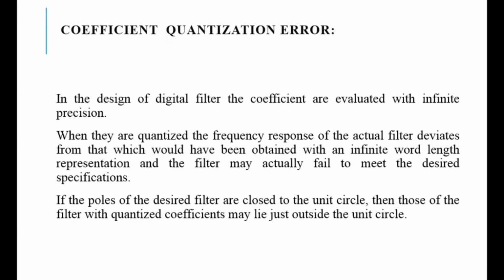So first let us discuss coefficient quantization error. In the design of a digital filter, the coefficients are evaluated with infinite precision. When they are quantized, the frequency response of the actual filter deviates from what would have been obtained with the infinite word length representation, and the filter may actually fail to meet the desired specifications. If the poles of the desired filter are close to the unit circle, then those of the filter with quantized coefficients may lie just outside the unit circle.